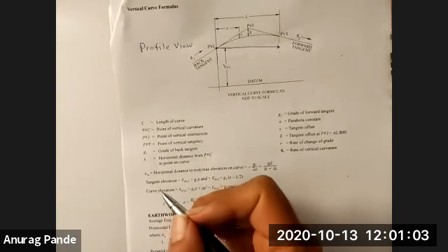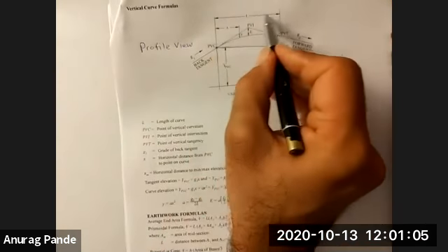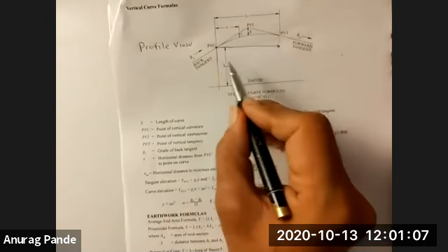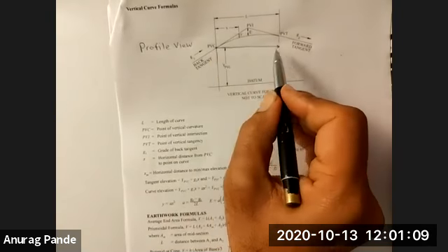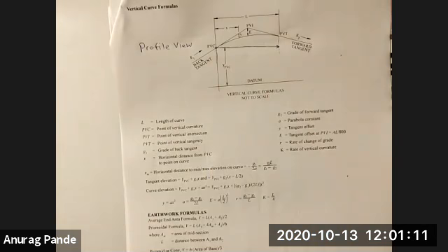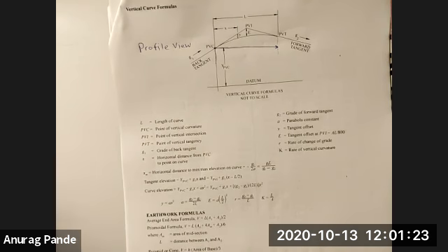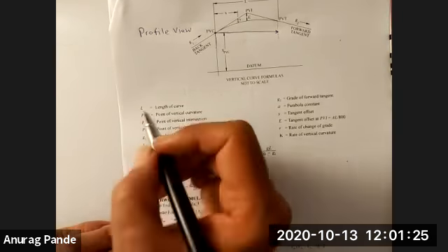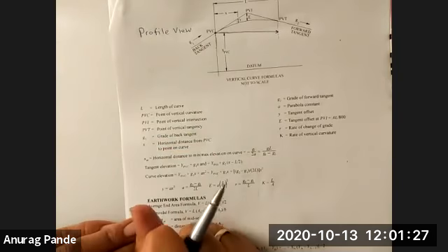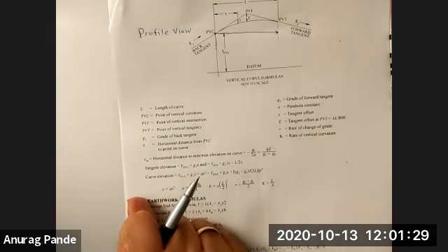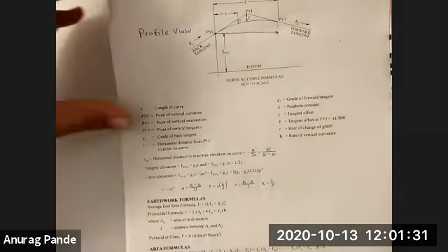So when you talk about the length of the curve, that is the straight line distance, as you can see here. Okay? So that's how we measure the length now. We do not measure the vertical curve length along the curve. We measure it as a projected point onto the horizontal plane. And remember, on the horizontal curve, the horizontal curve was the horizontal plane of the road. So that's something that we should keep in mind. And that changes the stationing calculation, the way we do it, and so forth.